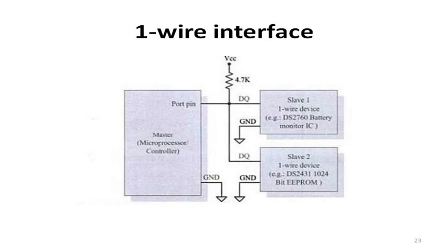Each device on the bus must be able to pull the one wire bus low at the appropriate time by using an open drain output. So if a transaction needs to be suspended for any reason, the bus must be left in the idle state so transaction can be resumed. So this is about one wire interface.